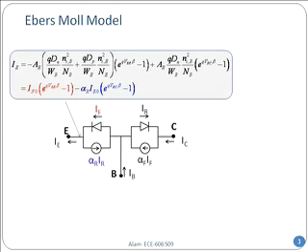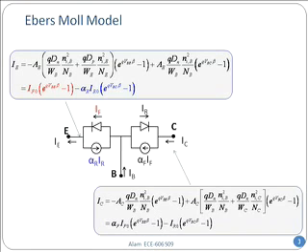That's by definition. And correspondingly, we had an expression for the collector current. You should check whether the signs look about right, corresponding to the direction of currents that we have shown over there. The difference between the collector and the emitter current, as you can see from the Ebers-Moll diagram, would be the base current, right? Because the sum of the three currents must be 0. So if you know these two currents, and if there is no current loss, electrons cannot be destroyed.